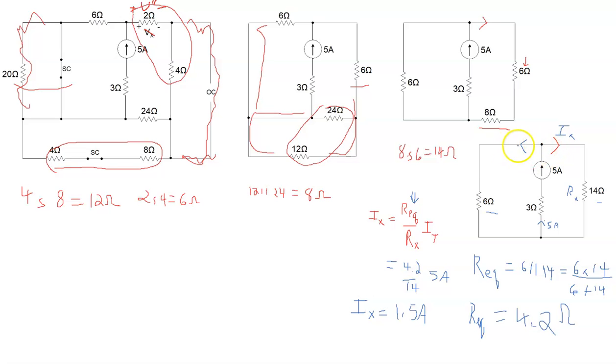Okay, great. So the 5 amp comes up here, divides at this point into 1.5 amps that goes our way, and a current that goes that way, which KCL will tell us 3.5. Okay, so it's the 1.5 going right that we're concerned in. Got 1.5 here then, got 1.5 here then, and so got 1.5 here, right? So from this original circuit then, we can say that V double prime is equal to Ix multiplied by the 2 ohms.